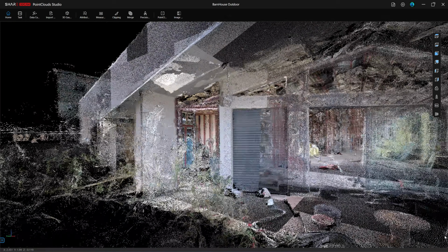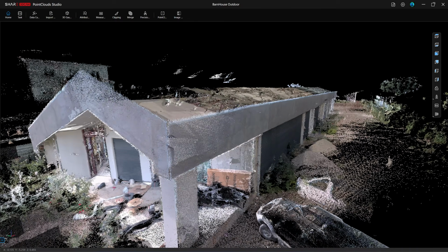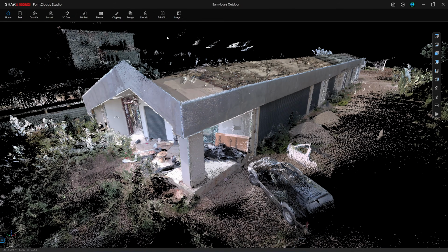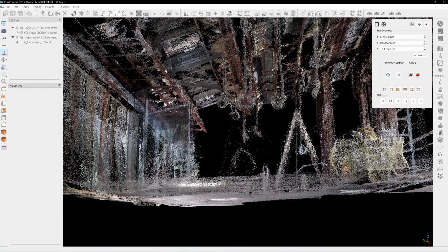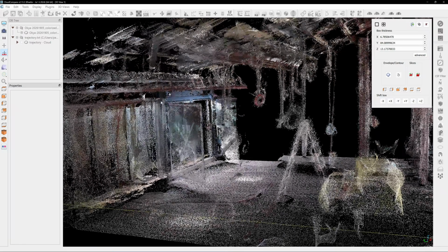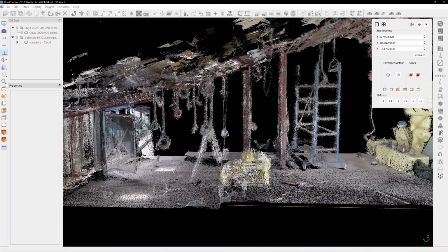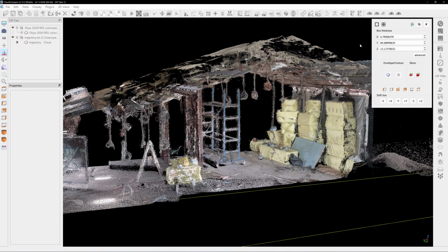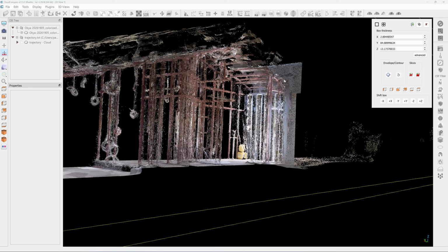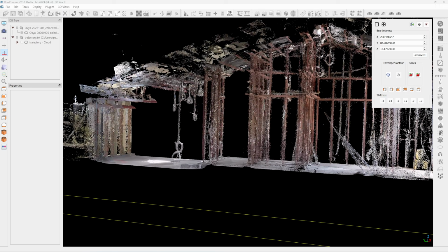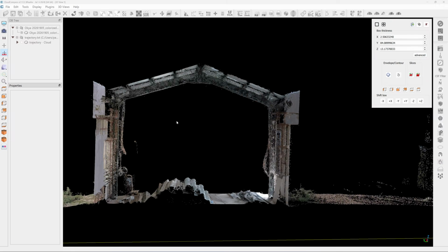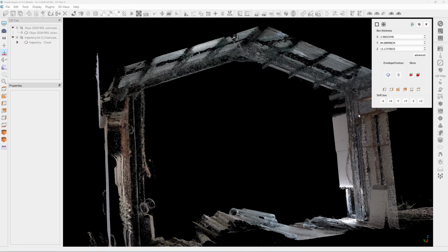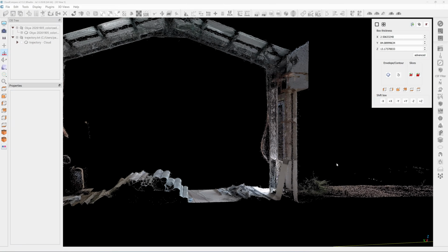The scan was done both inside and outside the barn, which allows me to define the wall thickness accurately. The scanning took about 10 minutes. The black main structure isn't fully captured because parts of it were blocked. That makes this scan more challenging to reverse. To handle it successfully, you need some basic construction knowledge. AI tools that automatically convert point clouds to CAD won't work in this situation.